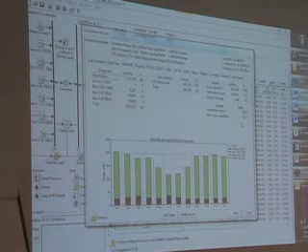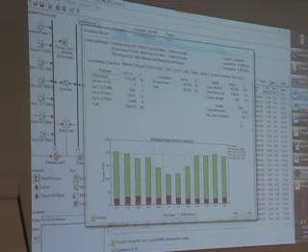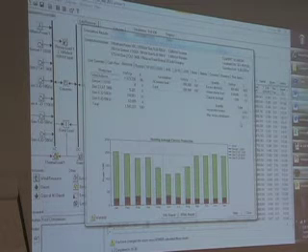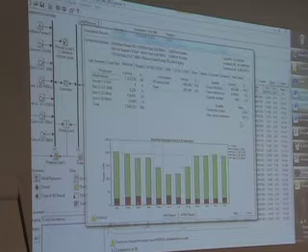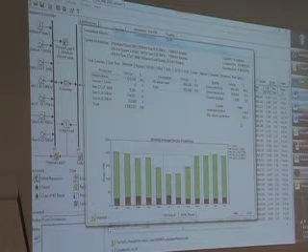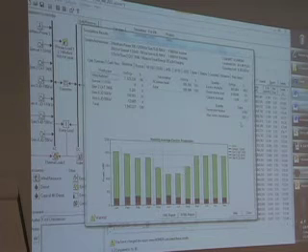And there's 8,760 time steps, and we just look at the highest number. So there was some hour in the year when the winds were putting out 5 times as much power as the load, which sounds like a lot, but you just need to have a place to put that power.